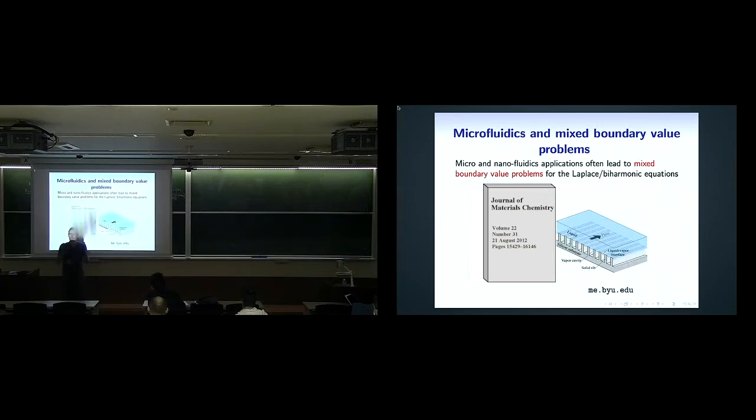So can you see the optimization problem here? You want to have free surfaces so that the fluid slips easily. But if you have too much free surface, the heat that goes through to the liquid deteriorates. So you've got to find the right balance between having just enough free surface, but not too much. Everyone understand?